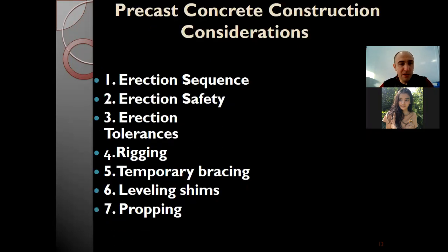And what about the precast construction techniques? If we separately discuss each of them, first is erection sequences. The precast concrete members shall be erected according to the pre-planned sequences. The erection plan is commonly prepared in drawings.